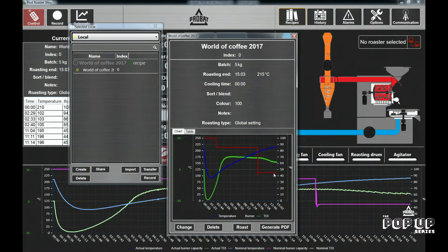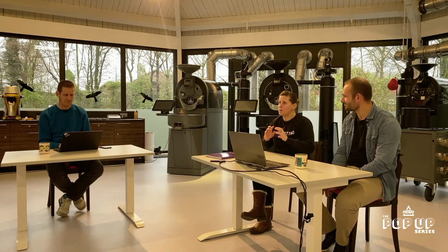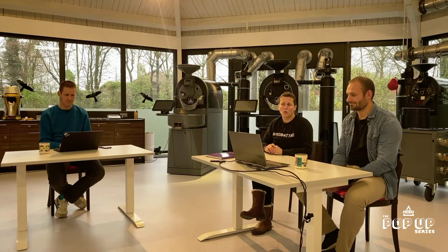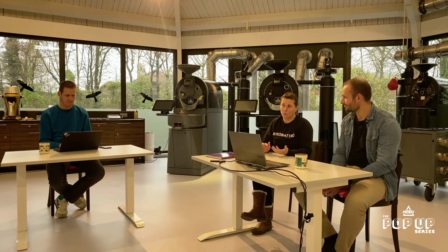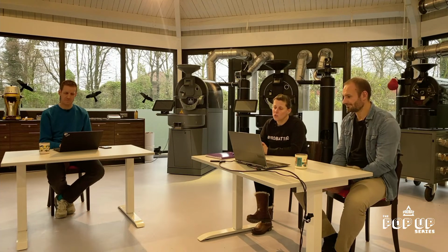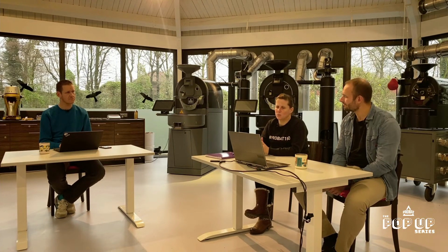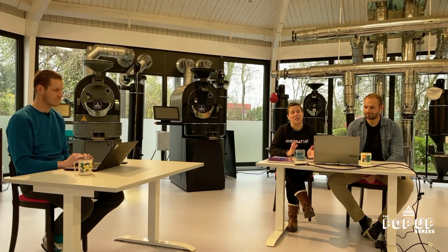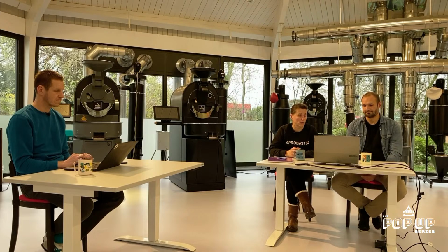And of course, just thinking of how roasting is going on, about all the outer circumstances that you could have, we do know that this of course cannot be used summer or winter, or different coffees, or coffees having different densities, different moisture content. So back then the roast master of course needed to be a little bit more controlling. So whenever there was a change in burner setting, we needed to check, is the curve still running the same? If not, we needed to adjust the burner, going a little bit higher in power or a little bit lower in power, just to meet our roasting curve.